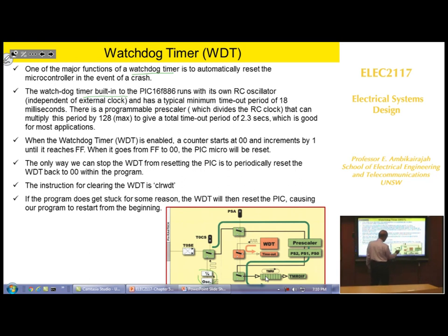So this Watchdog Timer built in there has its own oscillator. When you set it up in that Watchdog mode, it goes through this. Well, this one is the clock. Watchdog is this way. It has got its own timer, and the clock is fed in here through this and through this. You can feed here or you can feed it there. Just look at the diagram for further detail. It's very hard to explain. Yeah, this will create a pulse, and the timeout will happen after so many seconds, right?